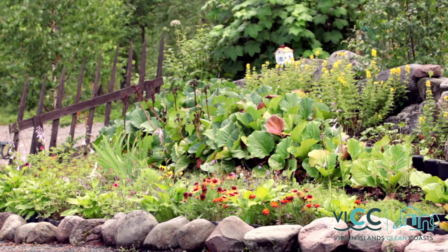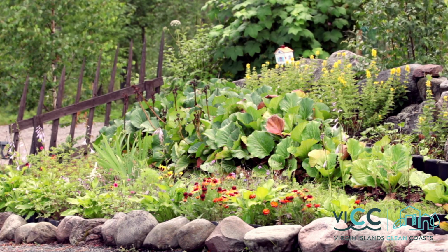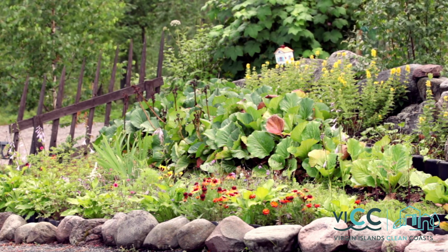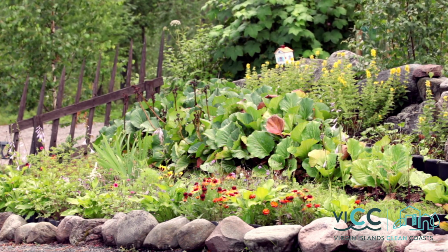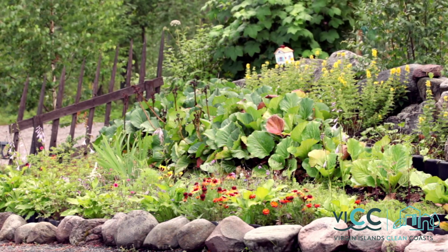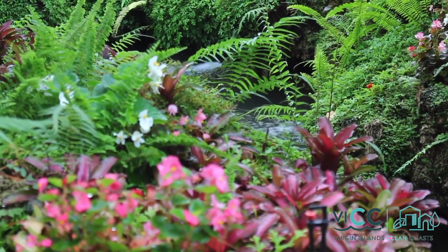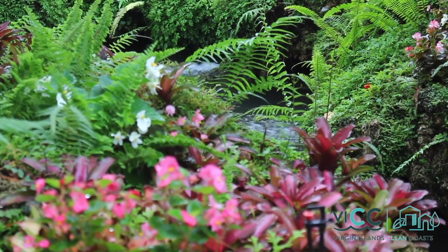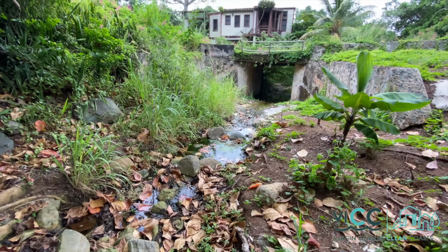Turn this area into planting beds. Fill these beds with plants to absorb stormwater, beautify the landscape, and provide other ecological benefits when you are done grading. Remember to mulch the area afterward to protect the soil from erosion. These 2 steps often solve simple drain and erosion issues, but if your problem is more complex, there is much more you can still do.